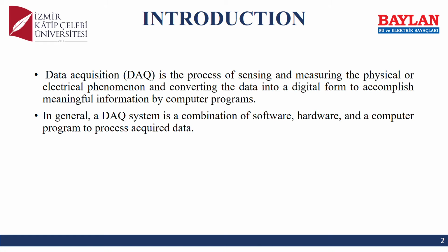The aim of this project is to design a data acquisition card with ARM Cortex-M4 processor and to ensure that this card is MATLAB Simulink compatible to control and process its interaction with the environment. The microprocessor performs data acquisition, functional filtering, and communication tasks. The library was created in the MATLAB Simulink environment for the control of this data acquisition card. In the system, the data acquired by the microprocessor is transferred to the computer via USB serial communication method.